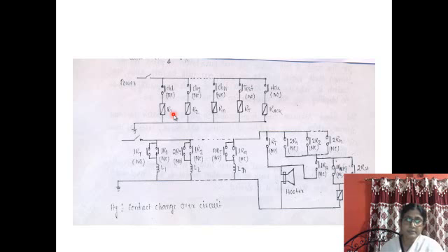As the relay R1 is in de-energized state, this normally closed path will make, to glow the lamp L1. So whenever any fault occurs corresponding to channel 1, that lamp will glow on.